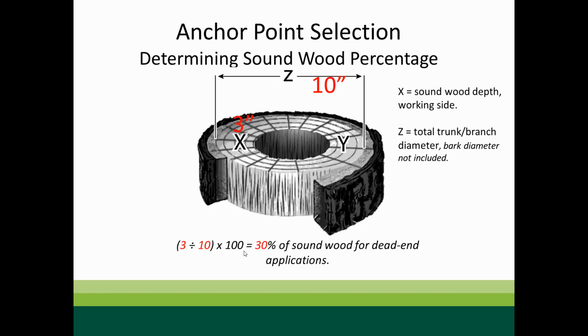You know, we're up there drilling. We're not looking at a cross section like in this picture, so we have to kind of use our educated guesses, right? When drilling through wood, if we drill slow enough, we'll feel a change in the pressure we need to apply to that drill to advance it.